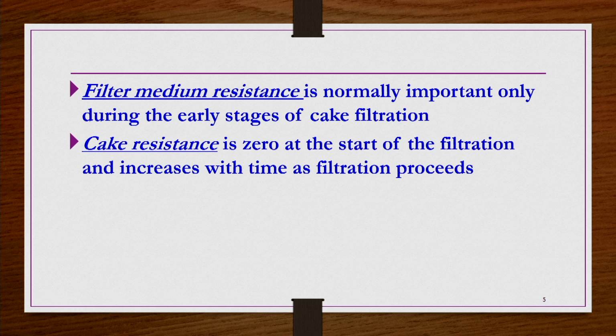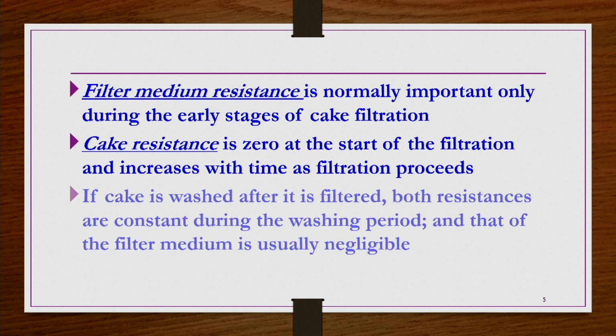Cake resistance is obviously zero at the start of filtration, because at the start there are no particles deposited on the surface of the filter medium, so there is no cake formation and no cake resistance. But as the filtration time progresses, more and more particles deposit, the cake thickness gradually increases, and hence the cake resistance also gradually increases with time as the filtration proceeds.